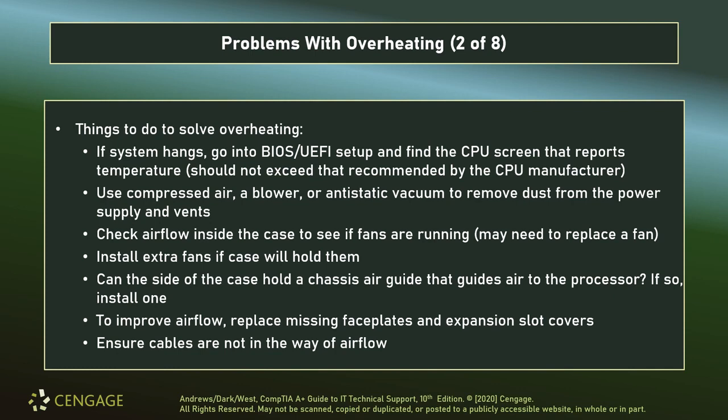Using a blower, compressed air, anti-static vacuum, that sort of thing. Check airflow inside of your case to see if your fans are running. Install extras if you can. Chassis air guides are not bad ideas. Those will guide air directly to your processor, being that that's usually the hottest component.